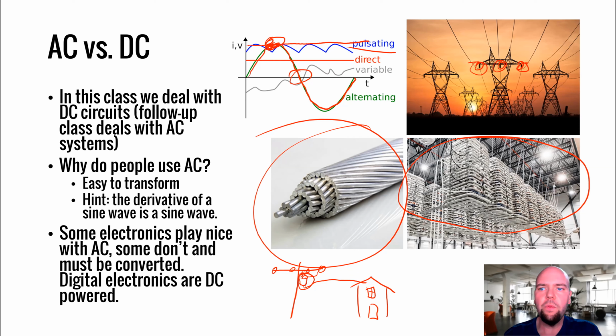When we have these conductors, the question is what metal do we use for these? Well, what's the most conductive metal out there? It's silver. The most conductive element is silver, but silver is really not popular. It's expensive and it's heavy and it tarnishes easily. Copper is a popular one. So do we use copper for these power lines?